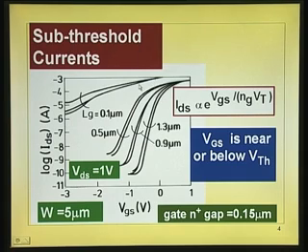But you can see there is a curve here from the threshold voltage, it is falling very gradually. That means, if I want to reduce the current by at least 2 to 3 orders of magnitude, I have to reduce the voltage from 0 right up to minus 3 volts, very large voltage. That is not a good sign. So, these things have been observed for the plots given here for different gate length.